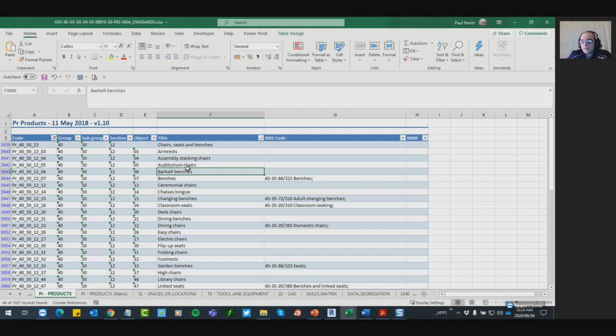One could use Dynamo or Navisworks. There is a way in Navisworks that you can use an XML script to read the coding and create selection sets, for argument's sake, if you want to do clash detection or 4D timeline or visualization.